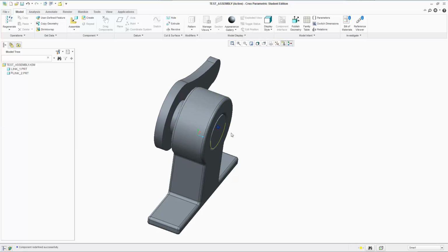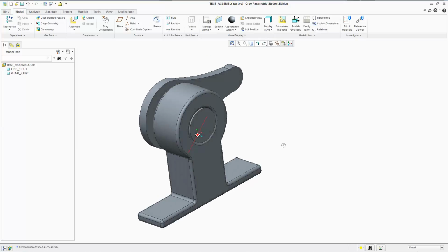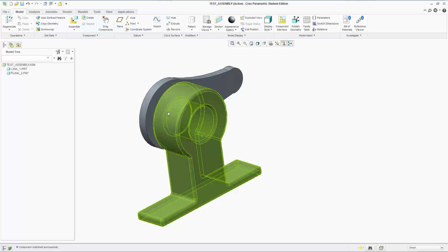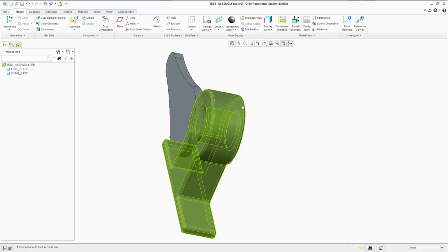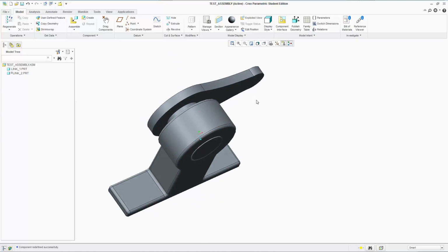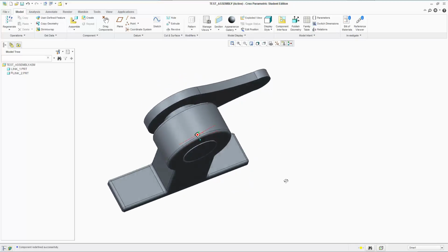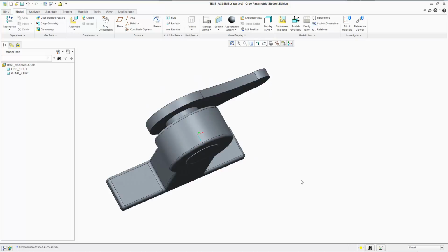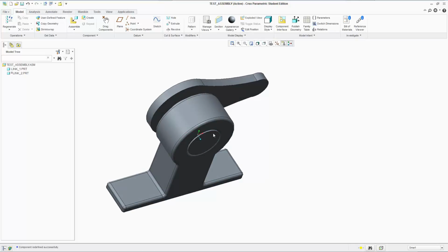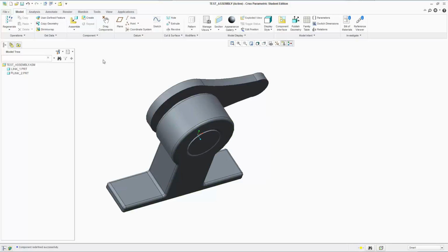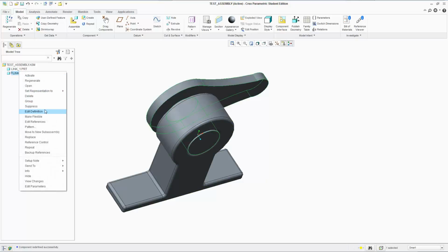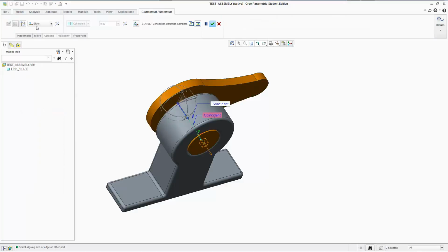And I guess this is to some degree synonymous to modeling a syringe or something, where you would have a fairly defined distance to which a certain push pin would be able to move, and it's not allowed to rotate either. I haven't really worked with syringes as much, but I guess you get the point. It's allowed to slide back and forth. So that's a slider connection, and I'm going to quickly go over some of the other connections that I don't really need to show.